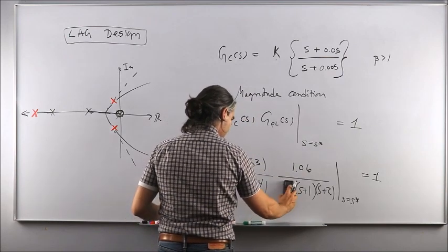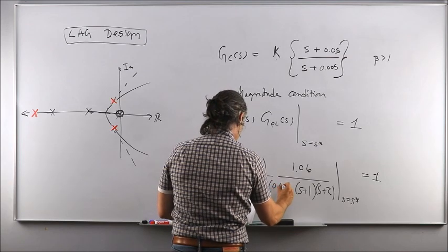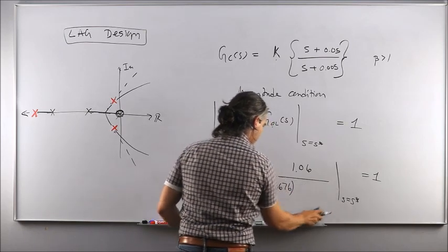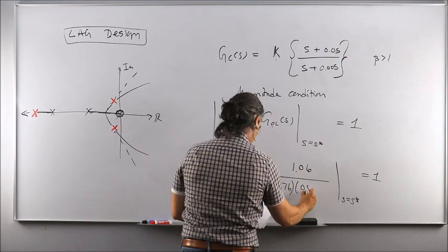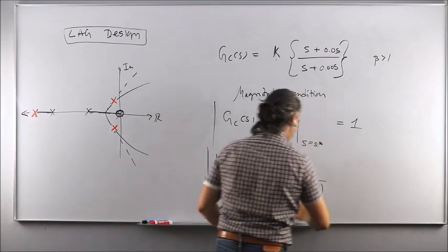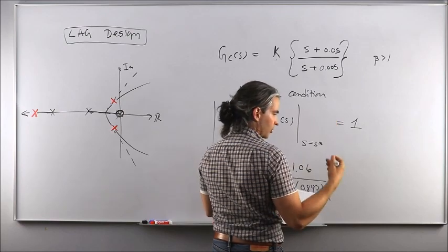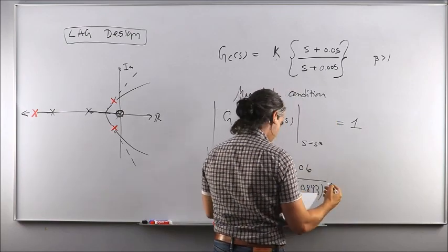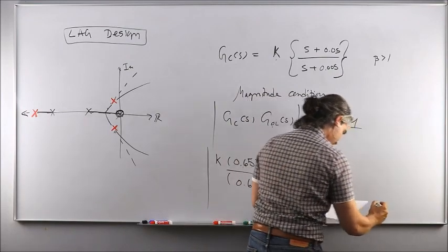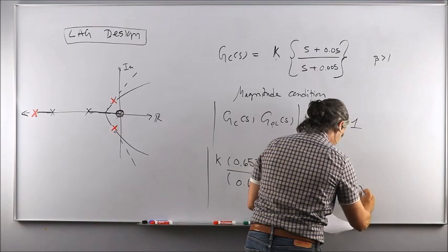The distance between the origin of the complex plane and S star will be 0.676. The distance between the pole at -1 and S star will be 0.893. And lastly, the distance between the last pole of the original open loop transfer function and the original closed loop pole locations, or S star, is going to be 1.77 maybe, question mark here. I can't even read my handwriting here.